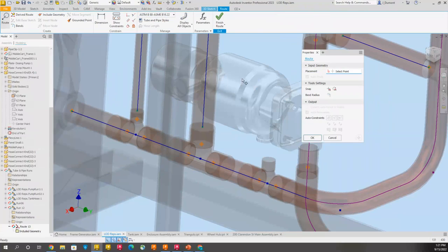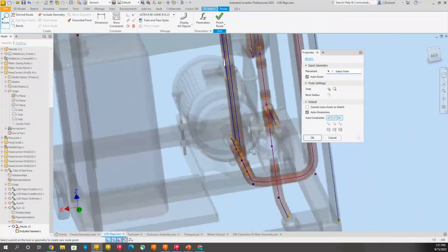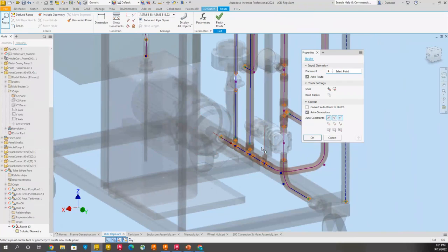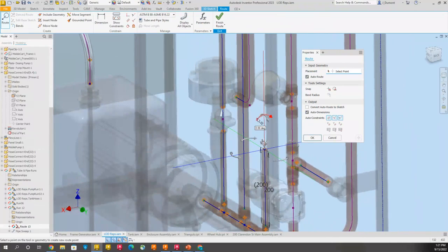Half inch, I'm gonna route it. Now from here, this time, I want to determine exactly how high up I'm gonna go. This is a metric assembly, so I'm going to come up 200 millimeters. I might need to clear other things or have other equipment going into this design. So at this point, I simply want to rotate it down 90 degrees.